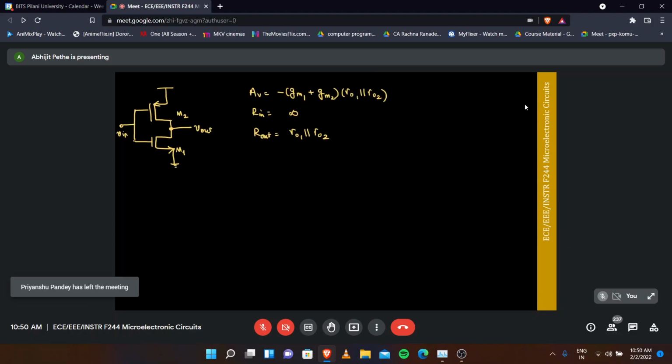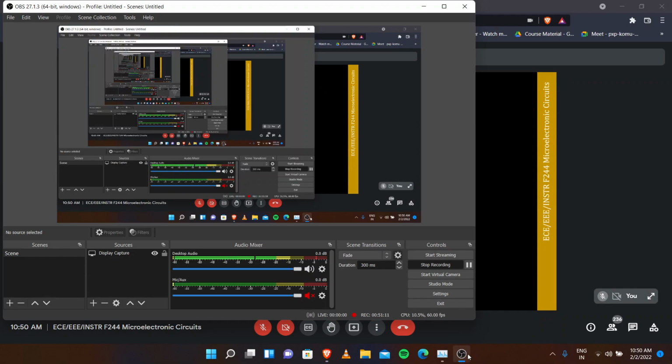Now, in the case when both the transistors are connected to the signal, what happens? Both the transistors are converting the input signal to a current, right? So Vn, when you apply it to M1 gate, M1 is converting Vn using minus GM1 Vn. Similarly, M2. Now the reason, Anant, why it adds and not subtracts is because this is a PMOS and this is an NMOS, right? So for example, let me suppose Vn increases.